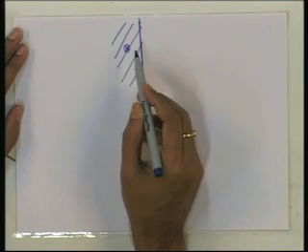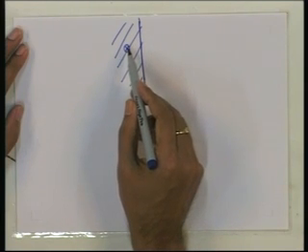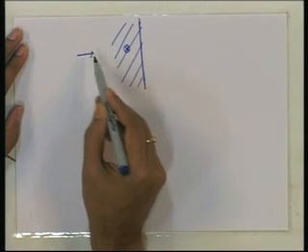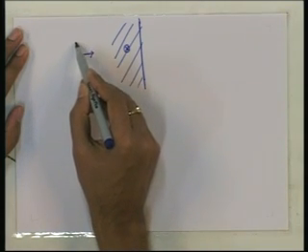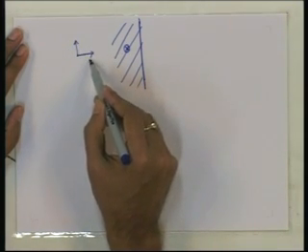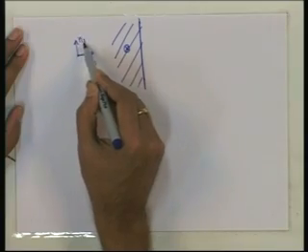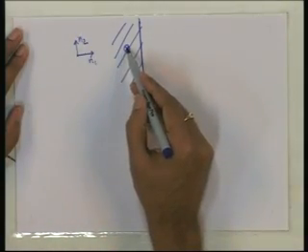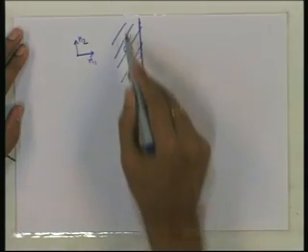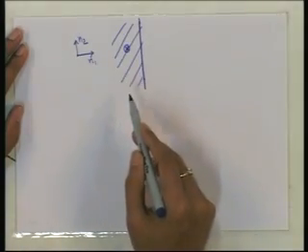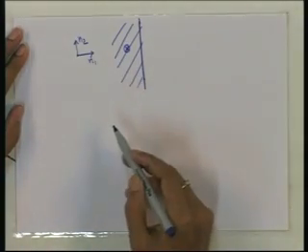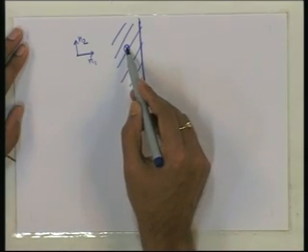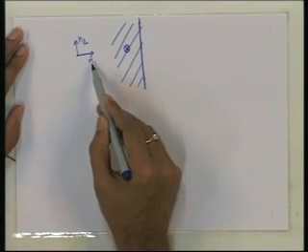Note that the received point depends only on the noise component in this direction. This is a two dimensional plane and there are two components of the noise, N1 and N2. N2 does not matter. If we transmit this point, whatever is the value of N2, it will still lie in this decision region. So, whether it is in the decision region of this point or not will be determined by the value of N1 alone.